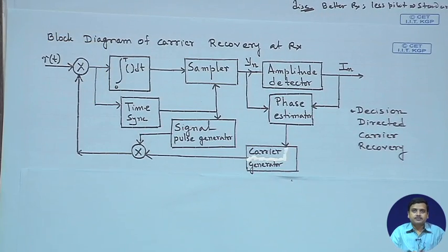have been translated to a block diagrammatic representation which is realizable. So, we stop the discussion on carrier recovery at this point, and just try to summarize that we have started with the philosophy of estimating signal parameters, we have used the log likelihood function, and we have made a parameter estimation using the maximum likelihood estimator. When we have finally arrived at the last phase of the estimation, the very important task is to read the expression carefully and try to see how the signal at each stage gets processed. Processing in the sense of multiplication, integration, summation, trigonometric operations like tan inverse and so on. We translate each part of the equation to the corresponding block diagram to realize the carrier phase recovery loop.